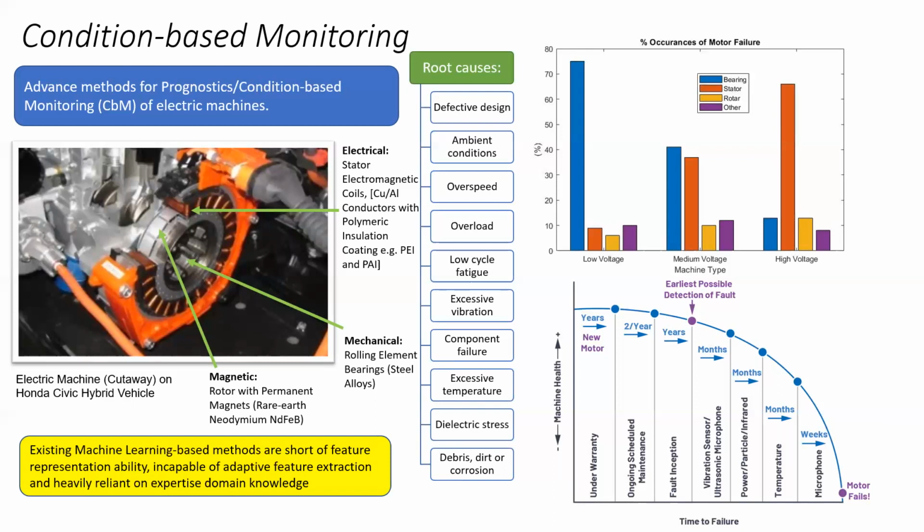A better option is a prognostic condition monitoring approach, involving an online monitoring scheme to give an accurate health state indication of when to perform targeted maintenance actions like repairs or part replacements. Generally, a condition-based monitoring system will incorporate 7 layers, which include sensors, signal processing, fault detection, health assessment, prognostic, decision support, and finally a presentation layer.